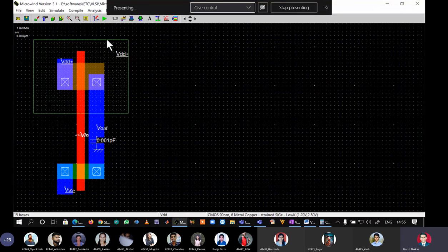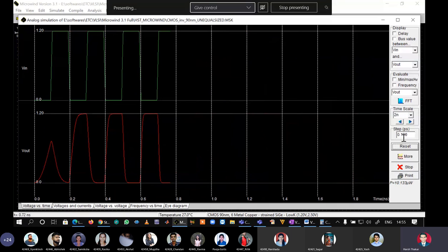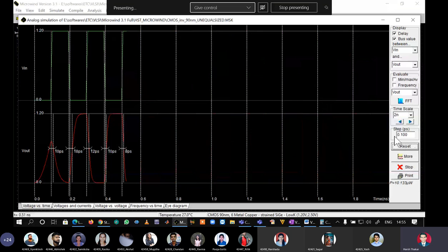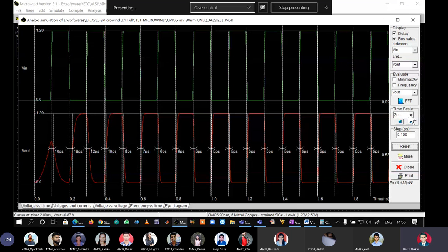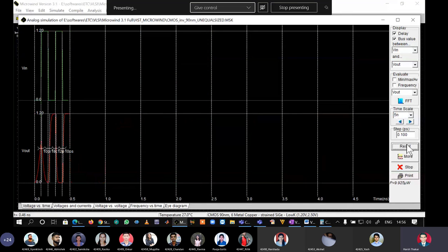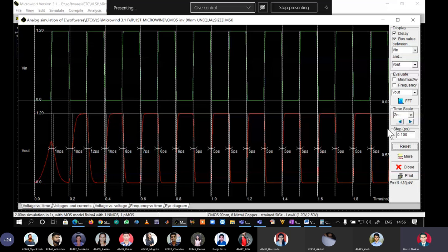This is a layout of a CMOS inverter where I have made PMOS 2.5 times larger than NMOS. See the simulation now. Okay. See, it is clear in front of us that the rise time and fall time have now become equal, 5 picoseconds and 5 picoseconds. You see, so it is becoming equal. Which is a proof.